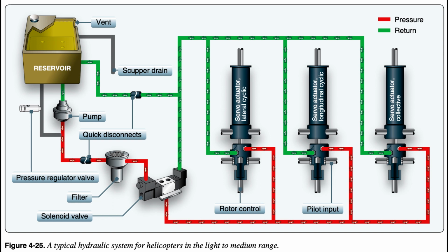When the switch/circuit breaker is put in the off position, the solenoid valve is now de-energized and closes, which then allows the pilot to maintain control of the helicopter with the hydraulic fluid in the actuators. This is known as a fail-safe system. If helicopter electrical power is lost in flight, the pilot is still able to maintain control of the hydraulic system. A pressure indicator in the cockpit may also be installed to monitor the system.